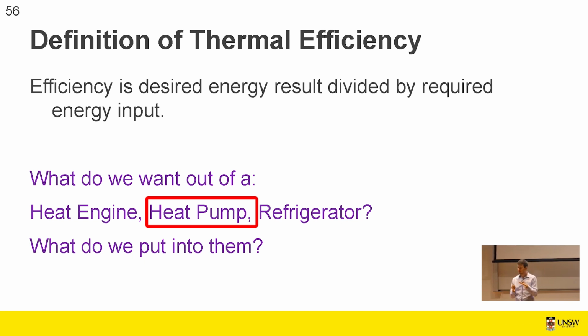It makes the wire hot, and that heats the water up. Okay, and so if you put a kilowatt of electricity through the wire, you lose that through the resistance in the wire, then the water has a kilowatt of energy added to it, and it gets hotter. Right? So that's a normal way to do things. Very simple construction, and it has an efficiency of 1 or close to, and loses some heat through the insulation. If you've got one at home, touch the outside, it's slightly warm.